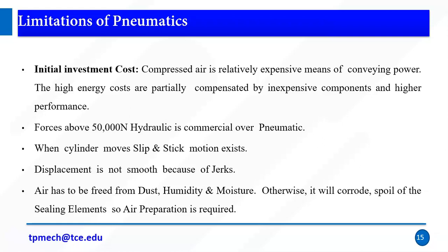For force above 50,000 Newton, hydraulics is more commercial than pneumatics. As I said earlier, only less than 50,000 Newton can we apply pneumatics. When the cylinder moves, slip and stick motion exists. So sometimes if you use pneumatics, the cylinder can have slip and stick motion. Displacement is not smooth because of the compressibility factor.